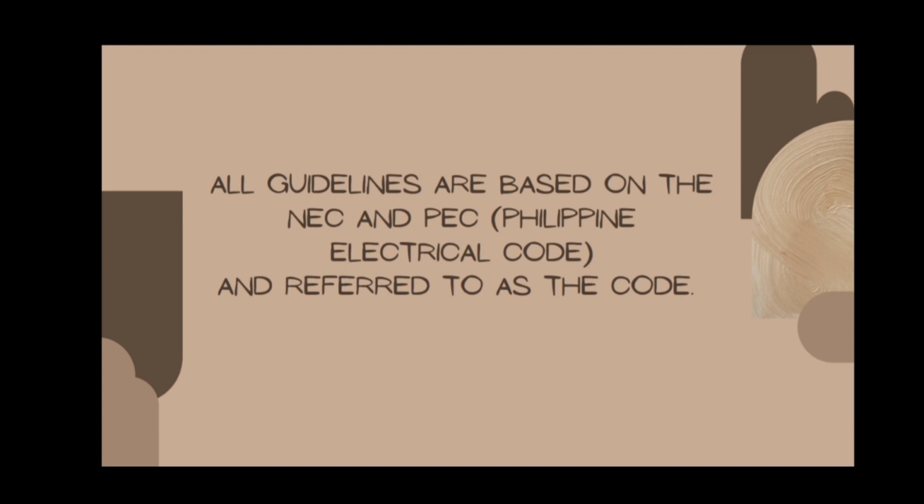Next, provide a special separate circuit for heating and air conditioning units. 11. Additional circuits similar to appliance circuits should be furnished to supply one outlet in each bedroom of a house that is not centrally air conditioned. Such outlets are intended for window air conditioners.